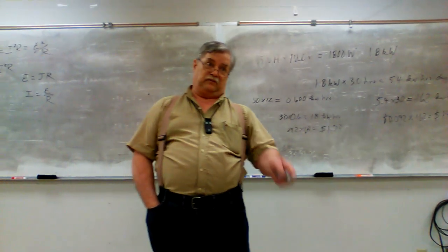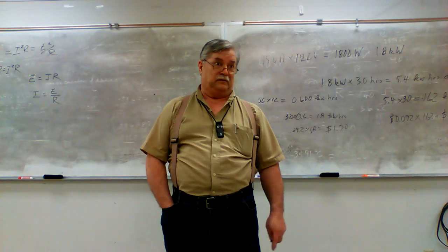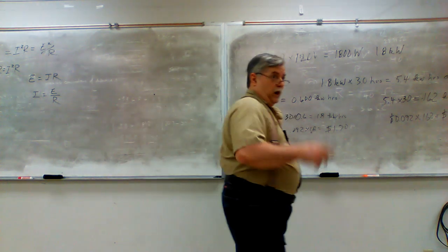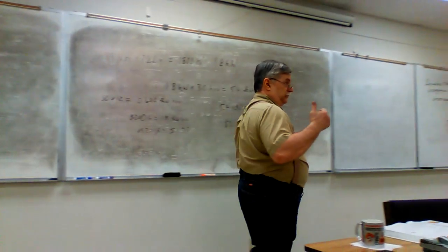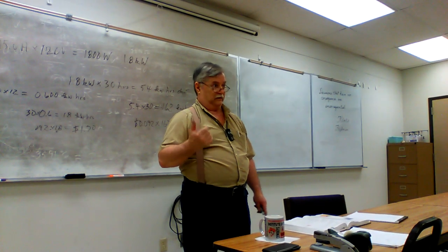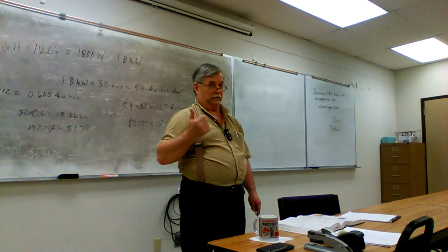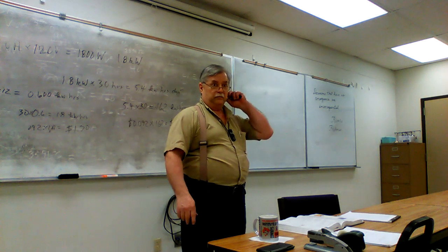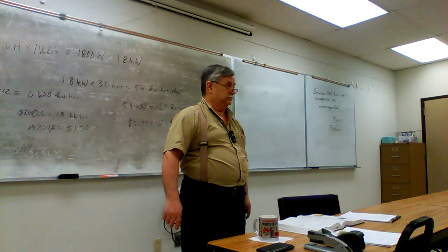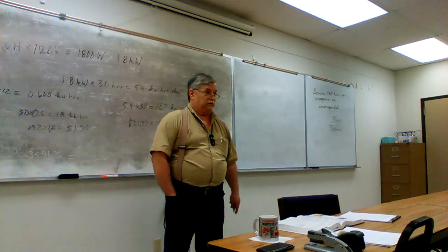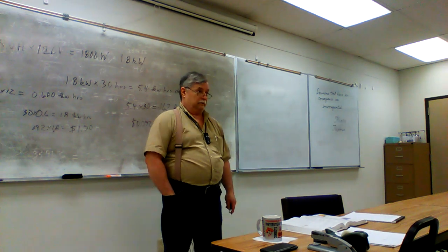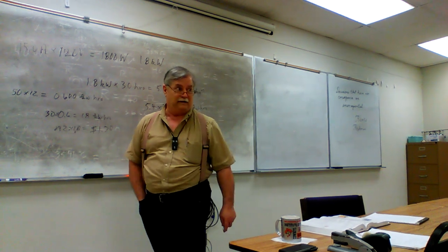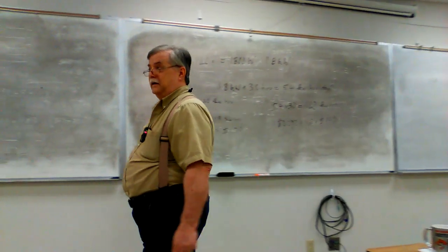They can't maintain a delta T of more than, I don't know, 40 or 50 degrees. So if you've got it set to 70 degrees inside and it gets down to 20, 15, into the teens outside, it's not going to be able to maintain that 70 degrees. So you're either going to crank it down to 60 degrees and bundle up, or more likely there's what's called an emergency heating element that will kick on in the plenum and heat the air to blow through the house. It is a 30 kilowatt device.